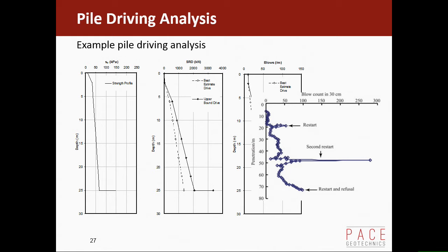Can you vibrate the end of the pile? If it refuses, can you vibrate the pile? Yeah, vibration works best in sands. It's not so effective in clays, and you can actually vibrate a pile into sands, but most hammers are impact hammers rather than vibratory hammers.